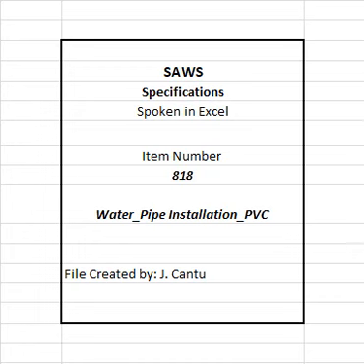818.7 Payment for PVC pipe water main installed will be made at the unit price bid per linear foot of pipe of the various sizes installed by the open cut method. One such payment shall also include tracer wire, detection tape, excavation, selected embedment material, backfill, compaction testing, polyethylene sleeve, hauling and disposition of surplus excavated material, including all existing pipe, fittings, appurtenances to be abandoned or removed, installation of all-weather surface, and other required testing as per specification item number 804, excavation, trenching and backfill.